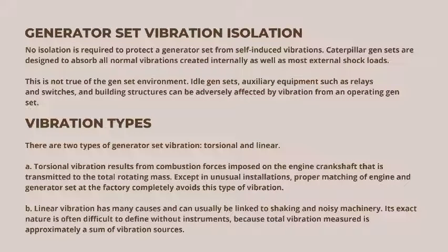Generator set vibration isolation. No isolation is required to protect the generator set from self-induced vibrations. Caterpillar gensets are designed to absorb all normal vibration created internally as well as most external shock loads. This is not true of the genset environment. Idle gensets, auxiliary equipment such as relays and switches, and building structures can be adversely affected by vibration from an operating genset.